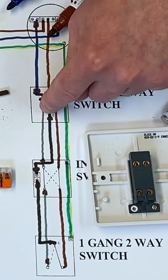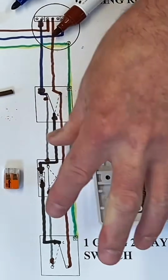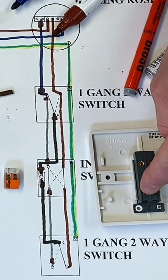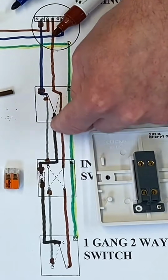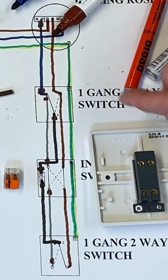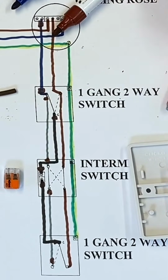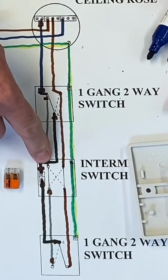And we've got this cable, which is our black one, just being connected in the back of the actual box, floating around. It's no connectors, only 4 in here. The Wago connector will pass the common loop through. Our CPCs are connected as usual, and there are connections. So that becomes our 2-way and intermediate switching.